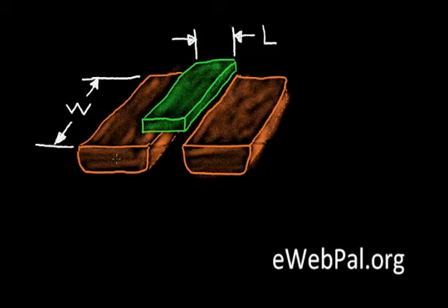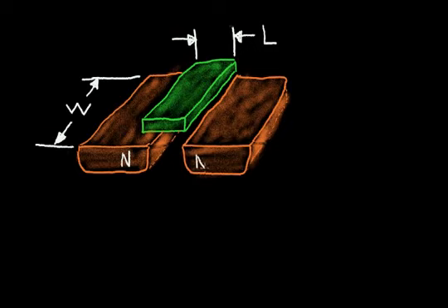Here I have an N-channel MOSFET where the orange is an N-type silicon and the green is a gate electrode. Now let's suppose that I want to ground the source region of my MOSFET, and to the drain I want to attach a capacitor with the bottom plate at ground, and let's say that this capacitor is charged up, and I want to raise the gate voltage, turn on this MOSFET transistor and discharge the capacitance, and I want to do that very quickly.